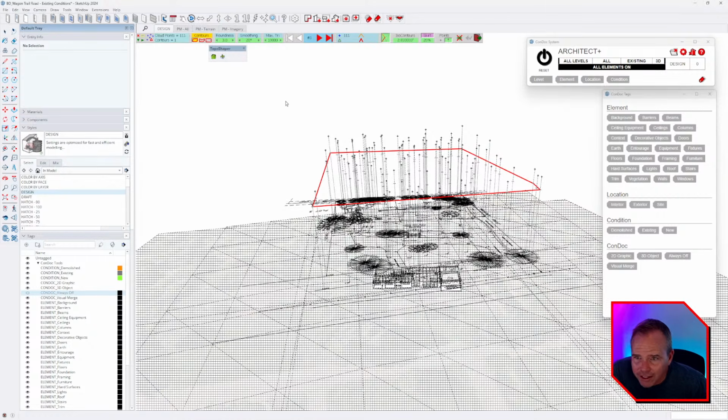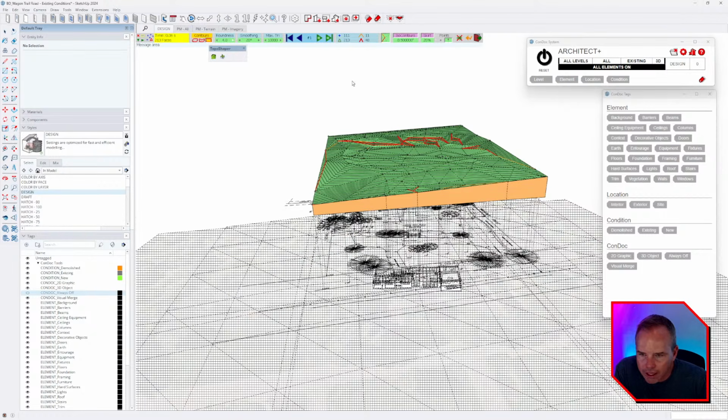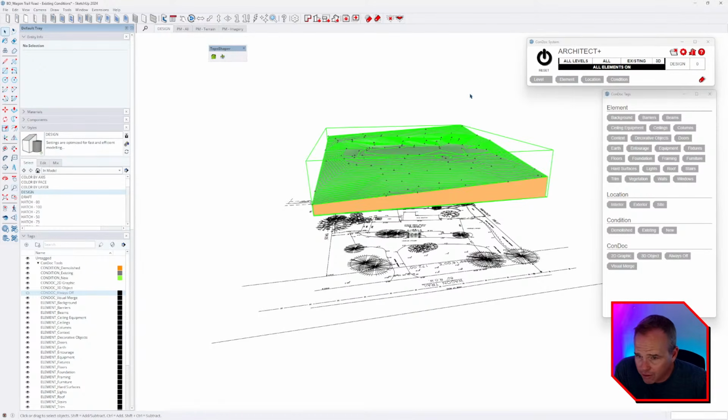But all right, so with Topo Shaper, we're going to start with this tri-mesh terrain. Oh God, here we go. And then, the gentleman whose tutorial I was watching used best fitting rectangle. He dialed up the roundness a bit, and we're going to want ISO contours, and we're going to want them at, I guess, a lot of them. So maybe every half foot. And then you hit play, and then you get something. And then we're going to hit exit tool. All right, that went way better than I expected it to go.